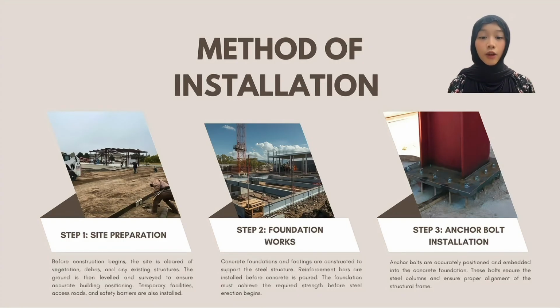Step 3. Anchor bolt installation. Anchor bolts are accurately positioned and embedded into the concrete foundation. These bolts secure the steel columns and ensure proper alignment of the structural frame.